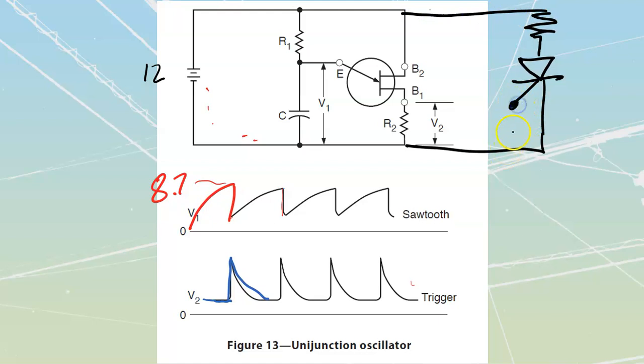And really, it's going to be my choice whether I want to attach this trigger device to here. If I do that, then it's going to have a low amount of voltage. It's got to be below whatever it takes to put this thing into conduction. But then every once in a while, when this thing jumps up, boom, it would push this thing into conduction. And then we would have conduction through here. At that point, we would have to wait until we lose our holding current on the SCR to shut it off. So, maybe this circuit shuts off or whatever.